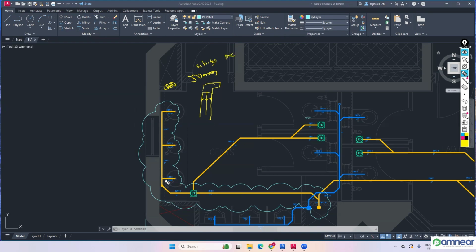For example, if you are using UPVC or CPVC, schedule 40, 50 mm, it doesn't mean that the internal diameter is 50 mm or the external diameter OD is 50 mm, correct? Nominal diameter or nominal pipe size is just a represented value until 12 inch, but from 14 inch onwards, nominal pipe size or diameter will be representing the OD only.